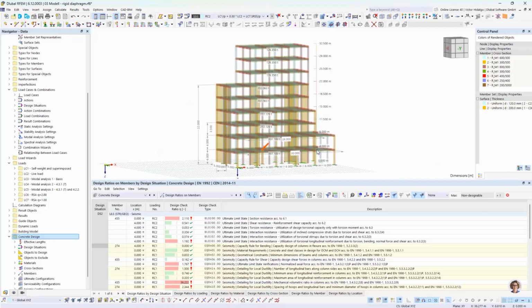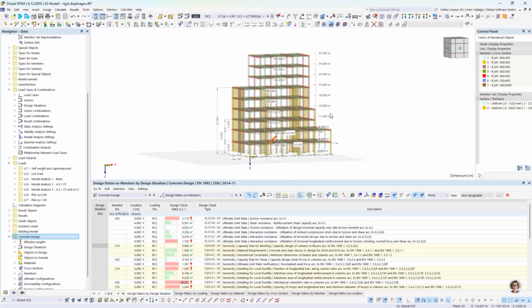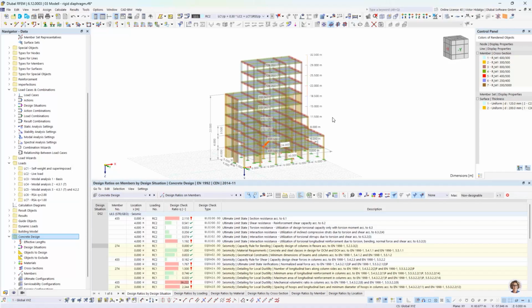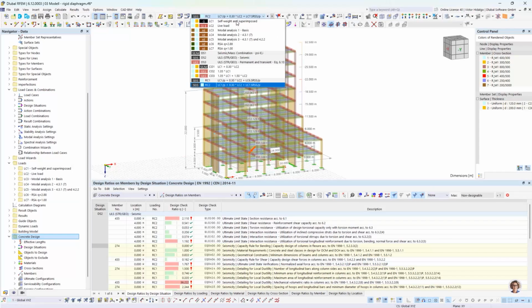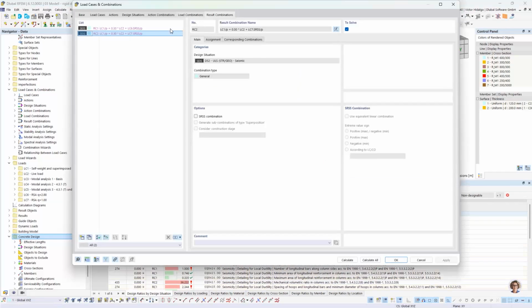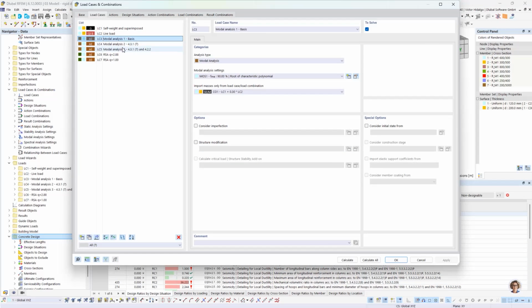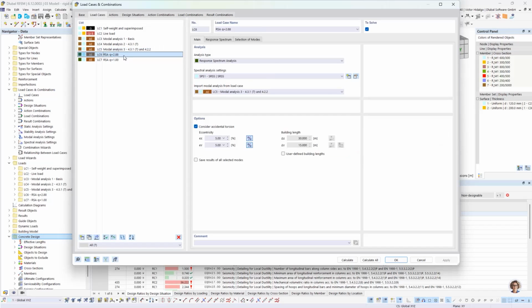Okay, here the final remark. And as a general conclusion, our hint for optimization process and iteration process. So I always mention that for the modal analysis, we have to make maybe 1, 2, 3 iterations to have a sense of results. Also integrated with the assumption in the building model add-on. And also, for example, the results for the response spectrum.